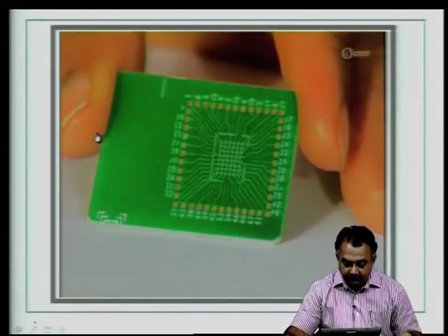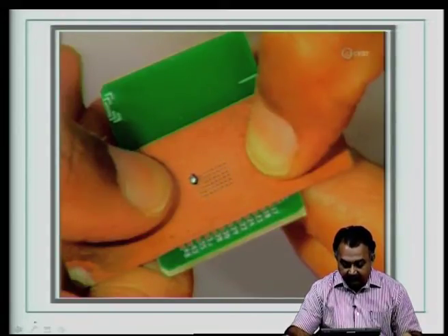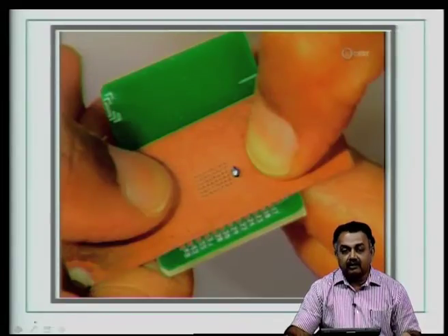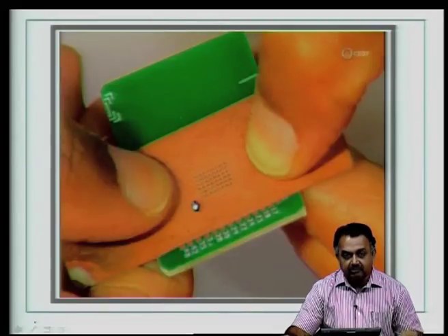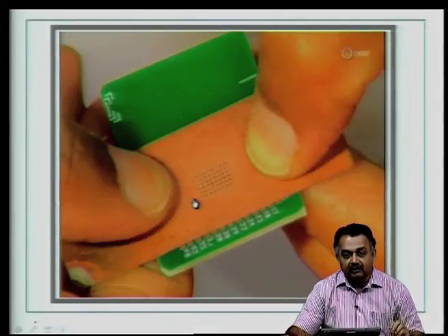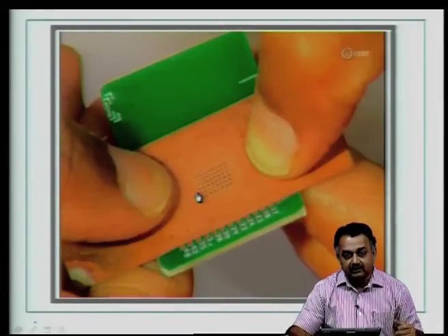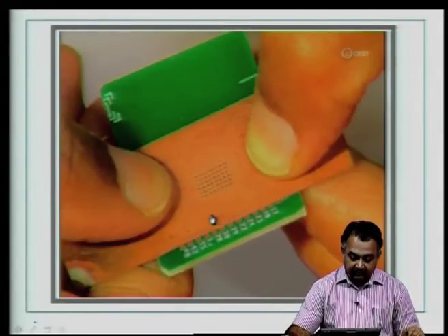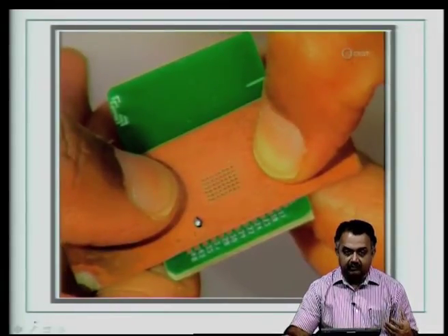Now, we are going to use a stencil. Here you can see that the patterns for the BGA have been created on a very thin laminate, like a Teflon or a BT epoxy or simply an FR4. So, this video shows typically how you can do this in your lab, which explains expensive processes like stencil printing and solder paste dispensing. So, here you have to align perfectly.